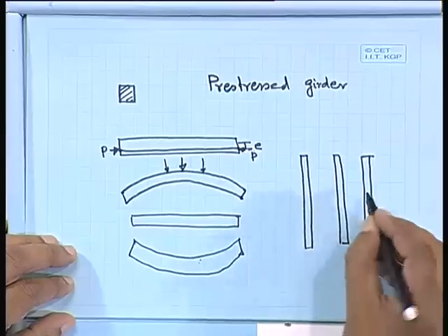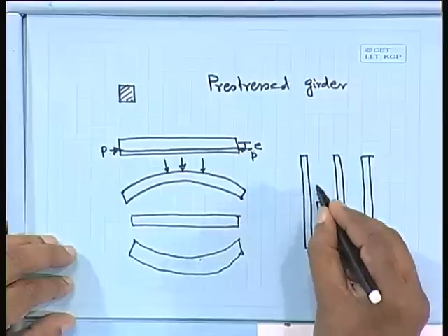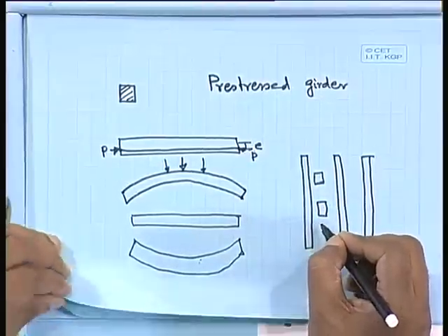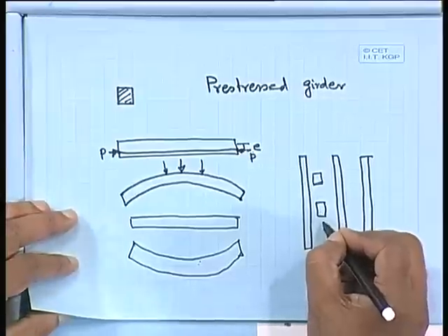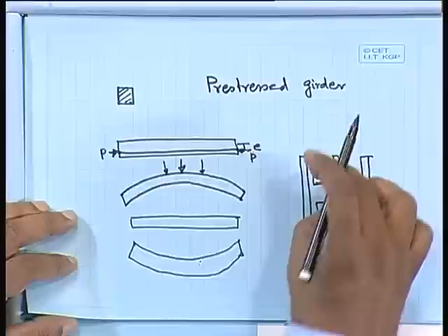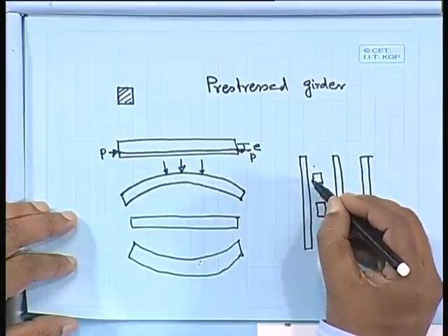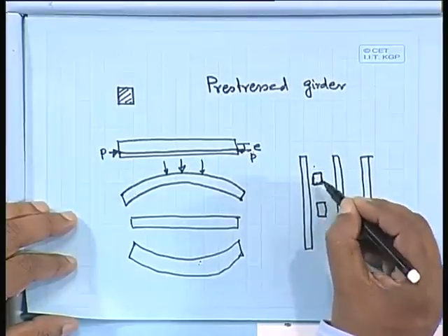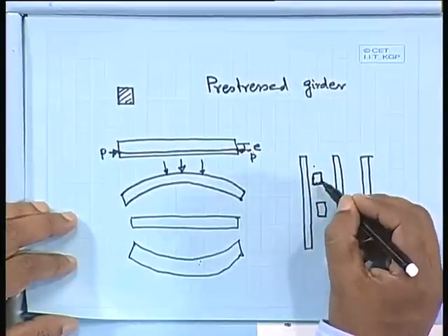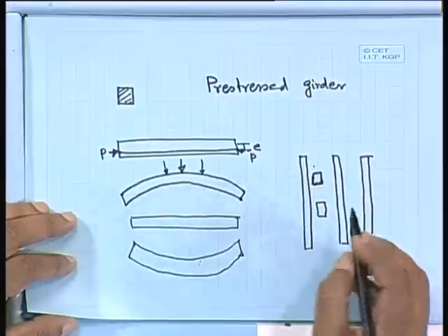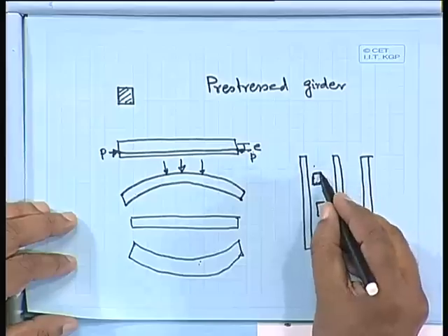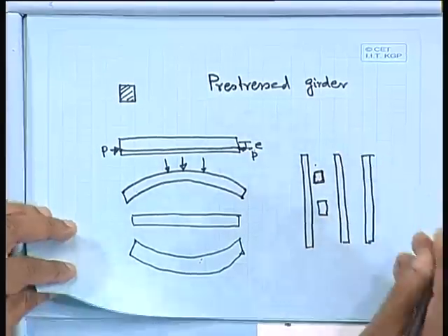Now here we have the wheel load. This wheel load comes as a concentrated load. If we have a concentrated load here, how shall we take the effective width of loading? We do not take the impression directly, we take a little more. How much more we can take, we have to find out. In this case, there is always one wearing coat.